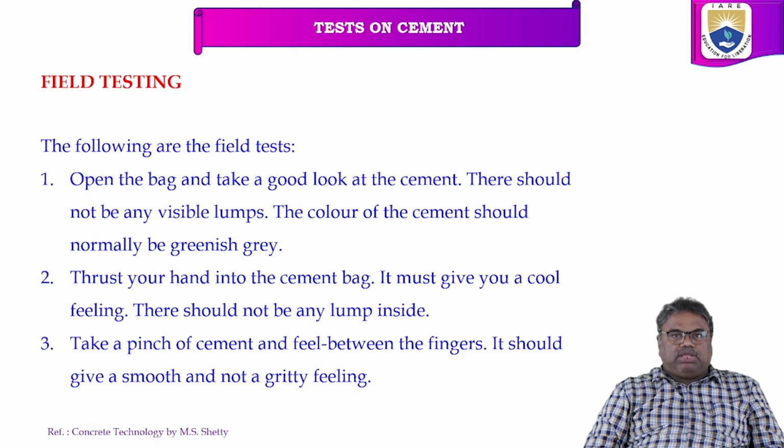There should not be any visible lumps, and the color of the cement should be normally greenish gray. Once you open the cement bag, you should see these two things: no visible lumps, and a greenish gray color. This is the first and foremost thing in the field test.